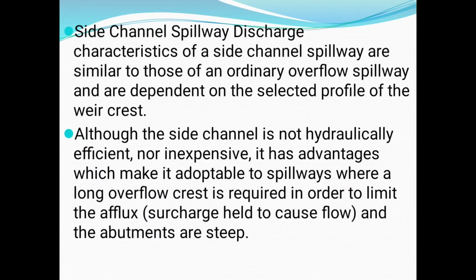Discharge characteristics of the side channel spillway are similar to those of an ordinary overflow spillway and are dependent on the selected profile of the weir crest. Although the side channel is neither hydraulically efficient nor inexpensive, it has advantages which make it adaptable to spillways where a long overflow crest is required in order to limit the afflux or surcharge head, and the abutments are steep.